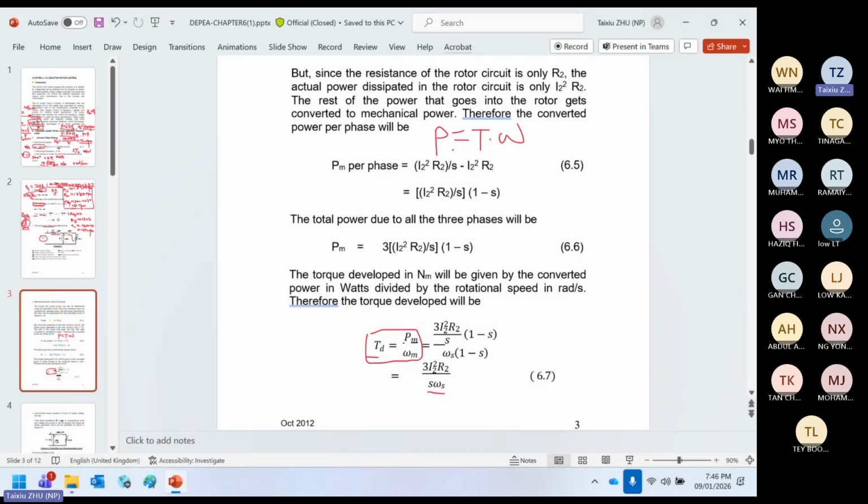Now say if the motor power is constant, fixed, like 10 kilowatts, then if you don't need a lot of torque, the speed can be higher. If you need a lot of torque, the speed must go down so that the product of the two is equal to the power of your motor. So this formula is very useful if you drive. If you are driving faster, that means if the road conditions are good, the torque is very little, then your car can go very fast, like on the highway. So basically these are three variables, and they are related to each other.